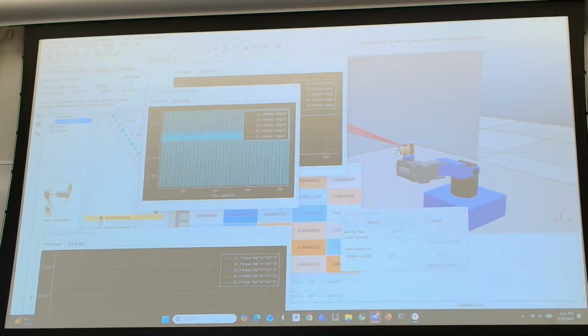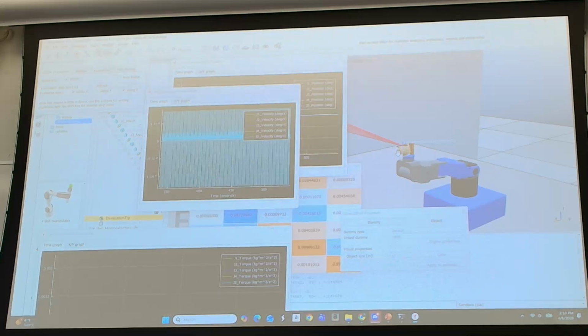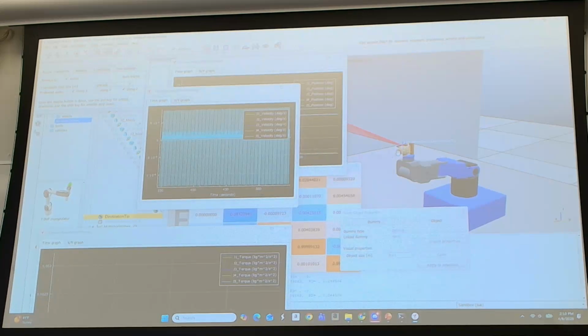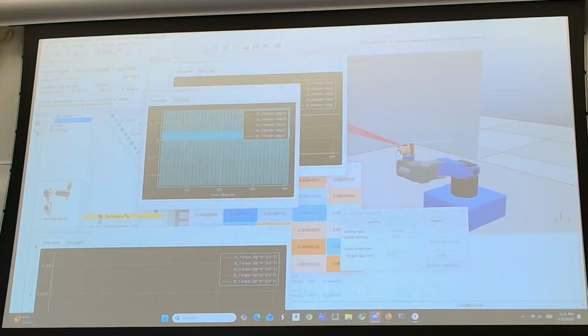Torque is a function of force times lever arm. Right. It's the function of force, and as the mass is constant, it's related to acceleration, right? Yeah. Higher acceleration, higher torque. What is torque proportional to? RPM? Current. Oh, current. So if I current limit, am I going too fast? Am I accelerating too fast? No. Yes. I thought you current limited. If I'm current limiting, if I hit the current limit, am I accelerating too fast?